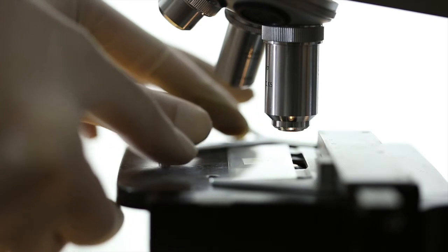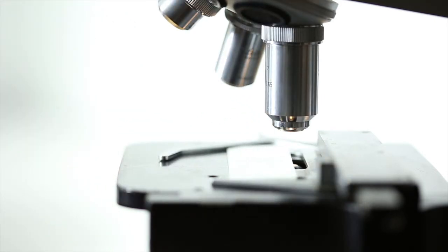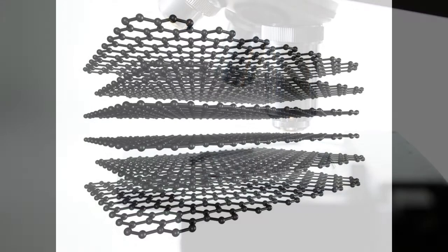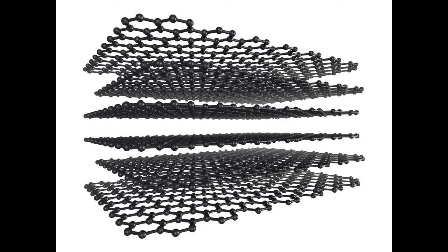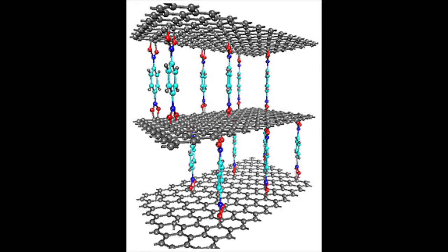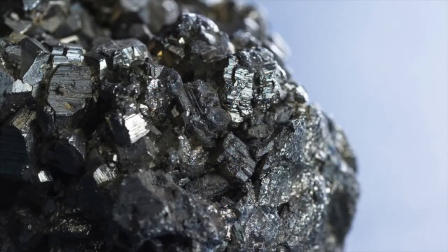The properties of graphene. Why does graphene not have the same properties as graphite if graphite is just many layers of graphene stacked together, one may ask. When you have so many layers of graphene stacked together, the strength of the overall bulk material is only as strong as the weak van der Waals forces between the layers and grain boundaries in graphite particles. The strong carbon-to-carbon covalent bonds in graphene are not utilized in graphite. Furthermore, thermal and electric properties are boosted when you isolate the graphene layers, as more electrons are free to move. More details about properties are found below.